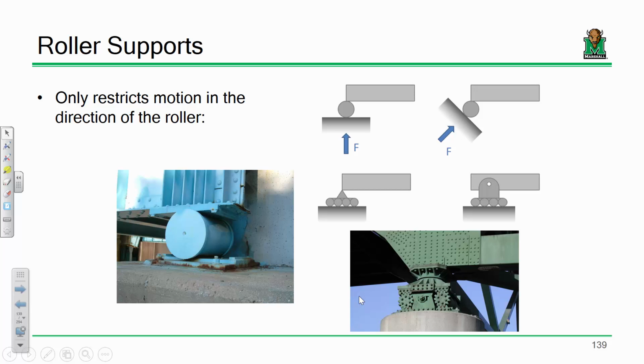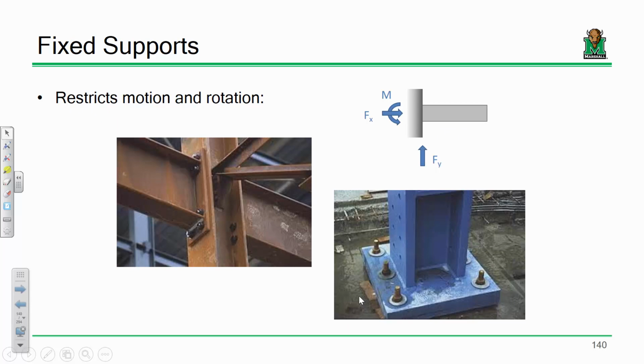If not, you'll start to get some thermal stresses built up in that girder, and those stresses can get pretty heavy pretty quick. And usually what ends up happening is you end up either failing the girder or failing the abutment, and so that's no good. So there's a real life example, but I just wanted you to get a flavor for that.